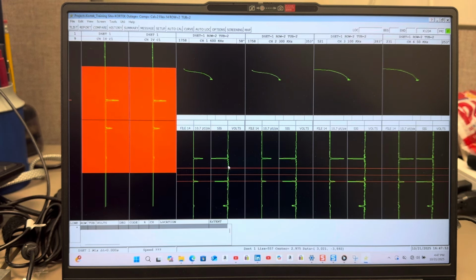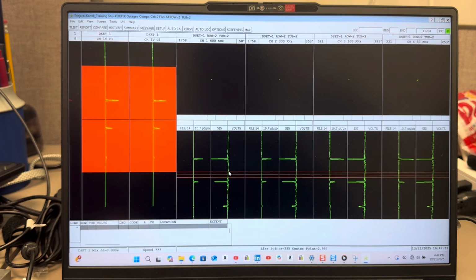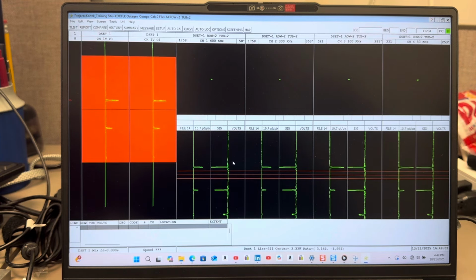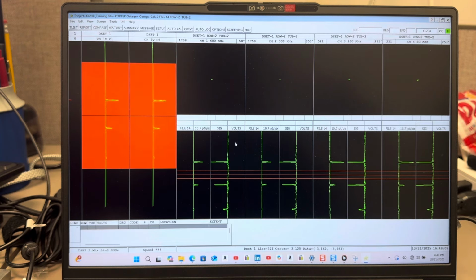Now if I go and measure on it, I'm adjusting these cursors by holding down my right mouse button and dragging the data down through my window. When you're scanning a material and you want to replicate your scan direction in the analysis software, the direction of probe travel is going to be from the top of the expanded strip chart to the bottom.